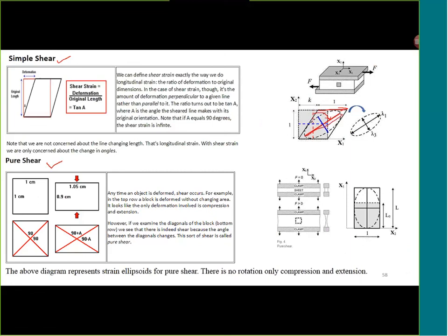due to the stretching of one diagonal and compression in the other diagonal, which can be viewed as, this shear can be viewed as a combination of stretching and compression, and also the material is rotated like this. This original flaw got rotated like this.